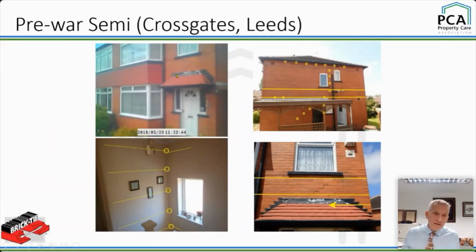Again, because of the width of this door, we've got a reduction there. We've got a blooming carport there that acts like a sail. It's getting lifted and pushed and lifted and pushed. And the wall, remember, because the staircase runs up it, it's the central bit where this is fixed. That hasn't got the lateral restraint afforded by the superstructure because the joists aren't resting in it. And that's why we've got a little bit of crack in there.